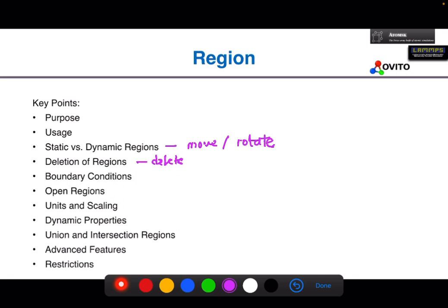So why do we need to use boundary conditions again? For example, you have defined your region as a block, and you want to make a particular end of your block free or fixed. For example, you want to fix this part so that no atoms come out through this particular wall. So you need to fix this wall or region. This boundary condition helps you in that regard. So you can use fix wall or region to fix a particular portion.